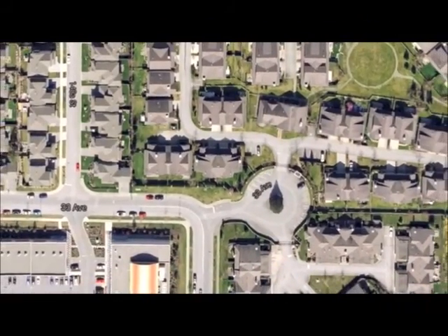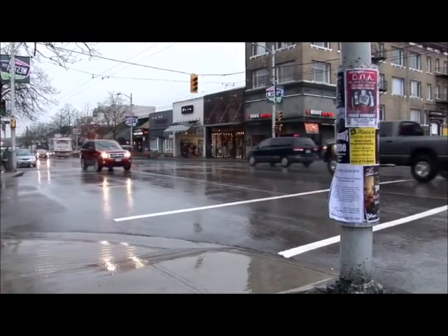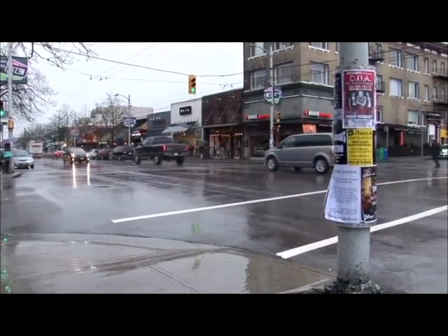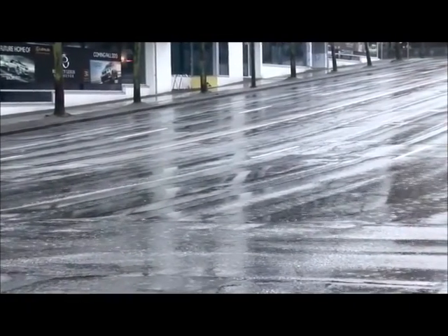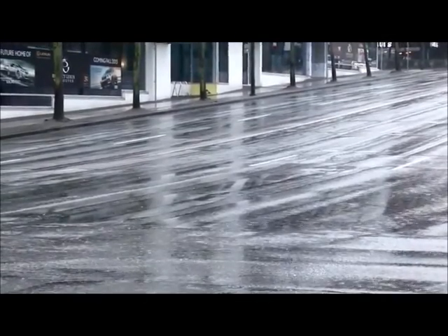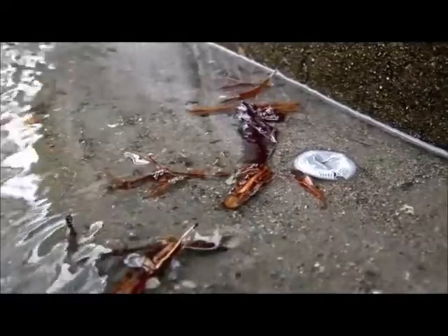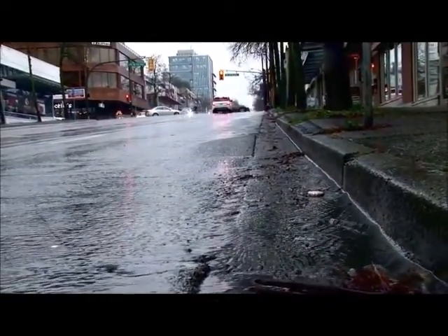When we zoom out from the property scale to the neighborhood scale, impervious surface area becomes much greater. Dense road networks, parking lots, and commercial and residential subdivisions present different stormwater management issues. These impervious features generate large amounts of runoff and high levels of pollution from vehicles, including hydrocarbons and metals. Runoff also contains sediments from construction sites and other activities. The increased runoff and contaminants pose challenges for stormwater management at the neighborhood scale.